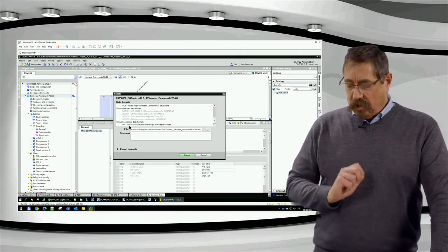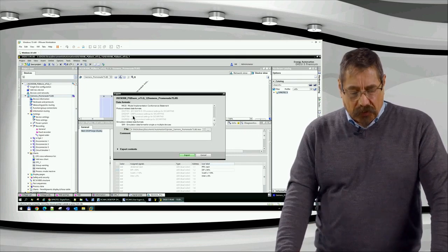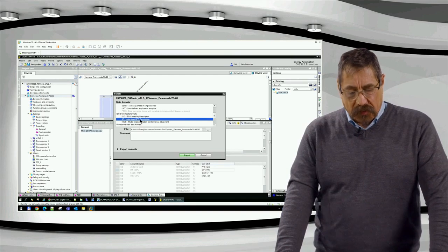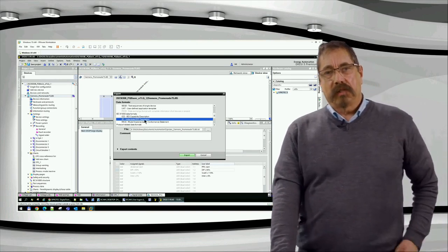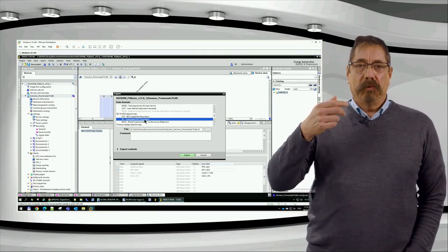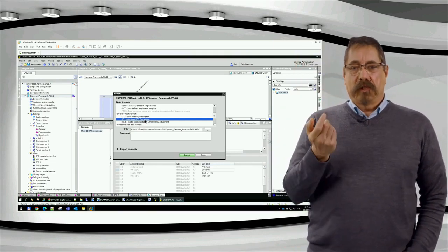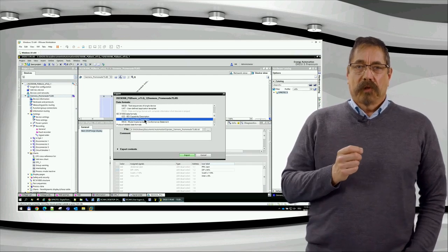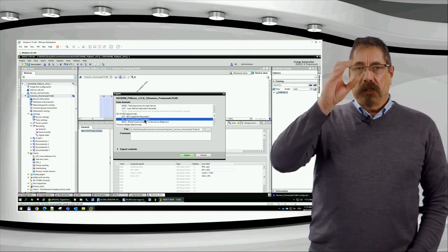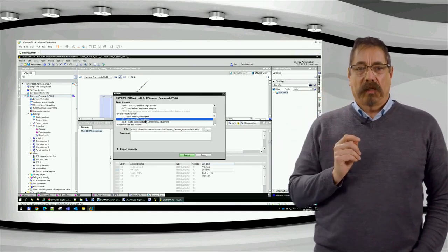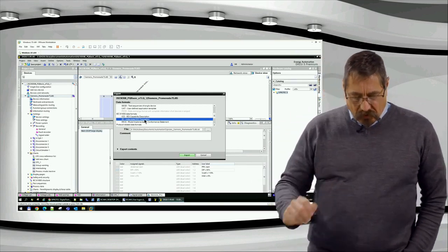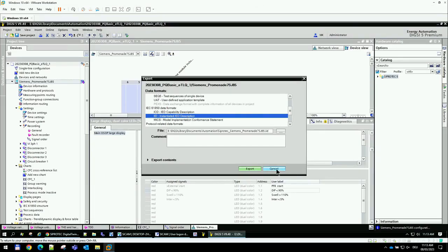The SIM will be imported into the digital twin, and then we are able to visualize the device. And a second piece of information that needs to be exported in this dialog is a so-called IID file, instantiated IED description, also based on IEC 61850. And this IID file we need afterwards to import into our substation automation system, the CCAM PQS. Yeah? And then the communication takes place between the virtual device, the CCAM PQS, and the CCAM PQ analyzer for visualization of such a fault record. So then let us do that.